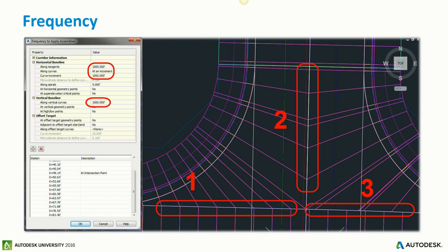This is not a big deal, but the slight contours, when they get created, are not nice enough in this area specifically. For the most part, Civil 3D does a good job, but sometimes this area will create bad interpolation. You know how the whole corridor is interpolated, from this point to this point to this point. So if you have interpolation from here to here, then here to here, which is good, then interpolation from this point to this point, that's going to make some difference. It's not straight and smooth.